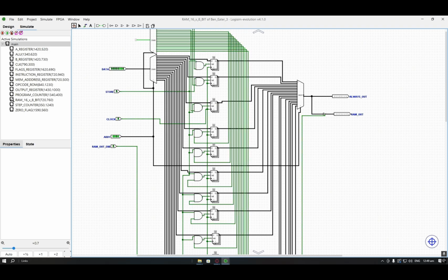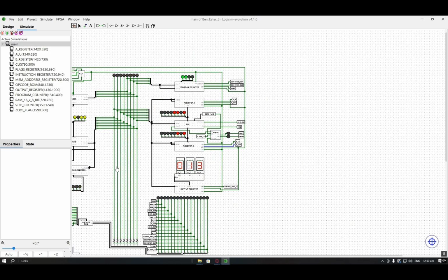What happens if RAM outputs during fetch? It would cause bus contention, which can corrupt the data or break execution. How do you switch between program and run mode? Using a multiplexer controlled by program mode that selects between manual input and CPU control.